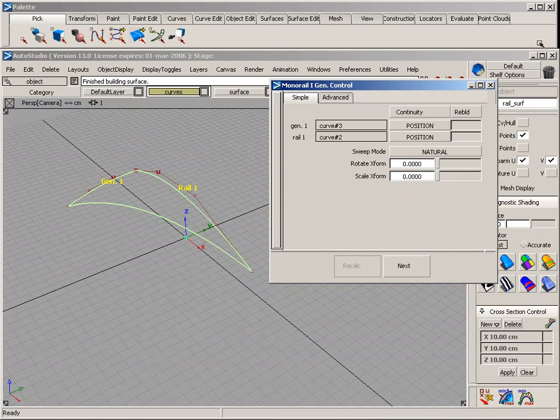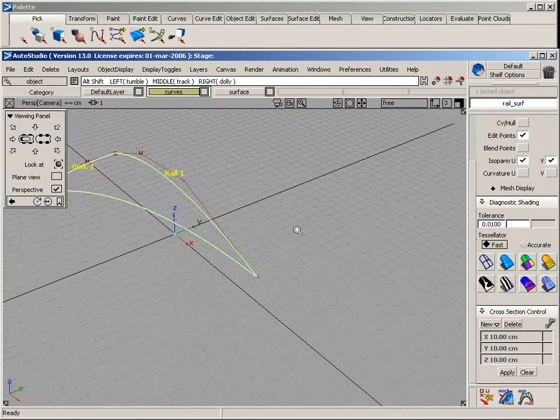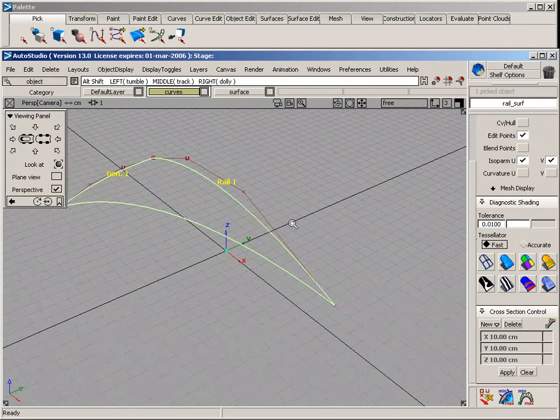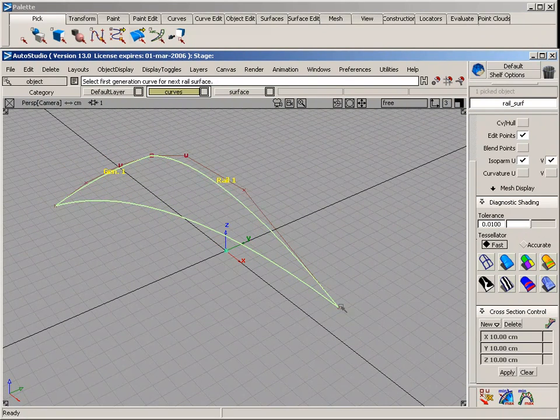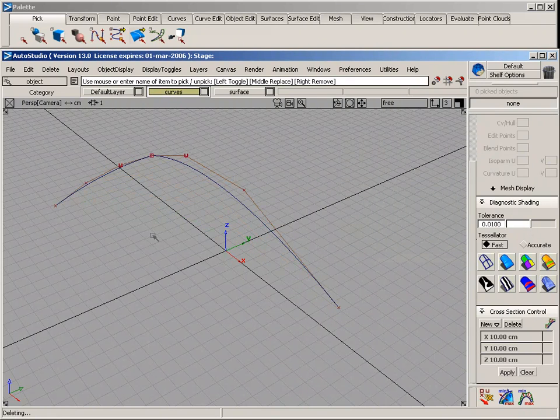Now, an important thing about this, making it come towards a point, this is scale 0, this is a good way of indicating a triangular surface. However, if you turn the CVs on, notice that the row of CVs, essentially in this location, are pinched together. Again, this is fine for visual representation, not for rapid prototyping.